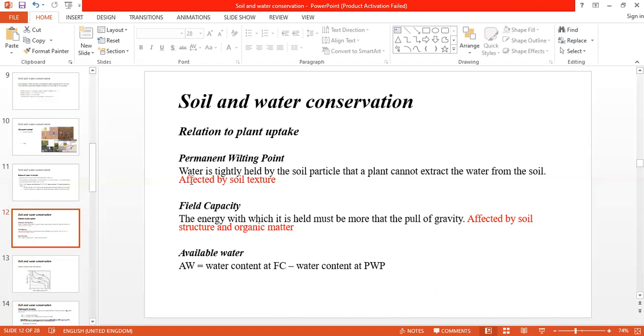When it reaches permanent wilting point again, you start applying water, such that you have a cycle. For example, when you irrigate in the morning today, for the water to dry to wilting point, maybe it takes 3 days. Meaning that your irrigation interval will be every 3 days. So you use this information to come up with such regimes of irrigation.